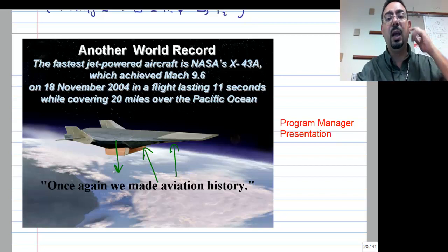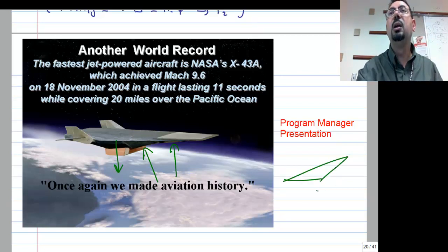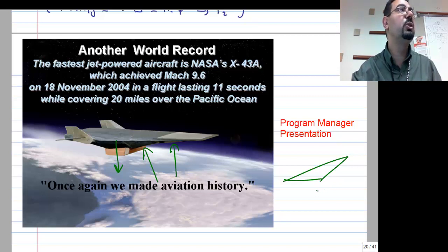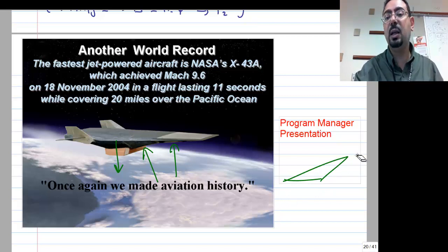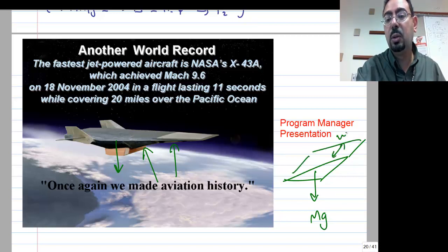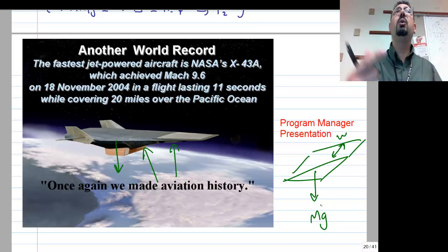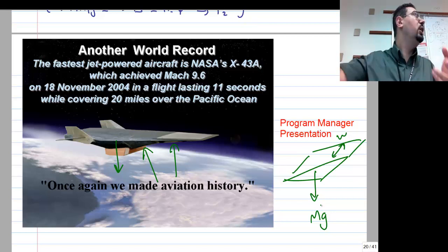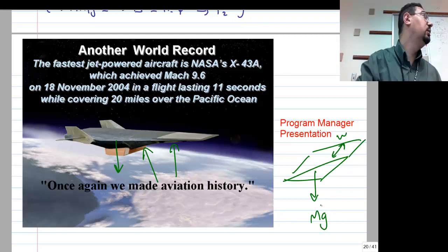that's supposed to carry the weight. So in one year, I gave them something like this, and I said this hypersonic or supersonic UAV can be approximated as a triangle like this. The weight is this much. How much is the span? How much is the width to be able to carry the weight? So how much is the span to carry the weight? All you have to do is generate the lift per unit depth and say that lift times the depth is equal to the weight. And from that you calculate the depth. Right?